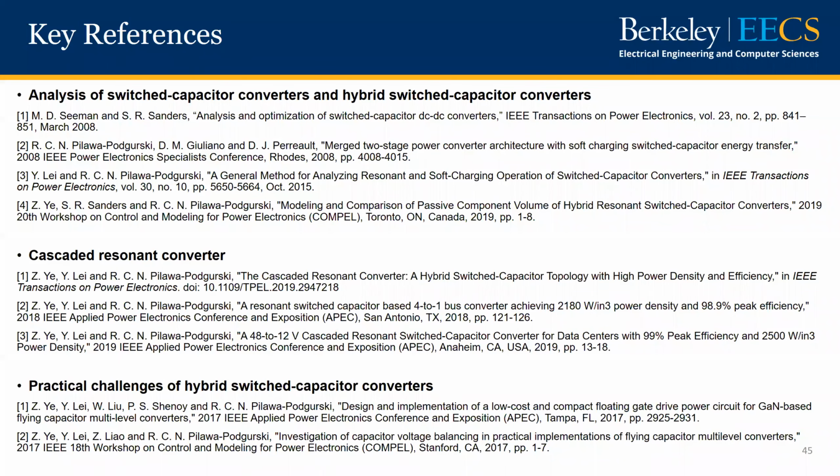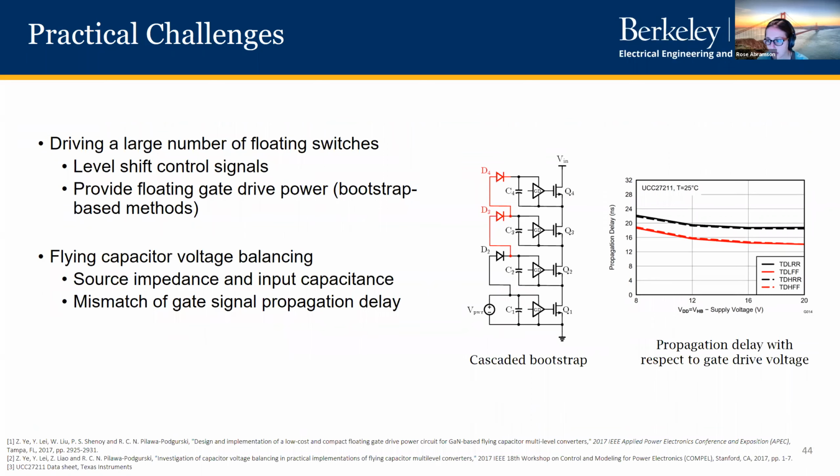Sure. So, for the bootstrap gate drive circuitry, this is an example of the bootstrap circuitry. You can see that we are connecting multiple gate drivers together with a bootstrap diode to run them off of a single rail, this V power.